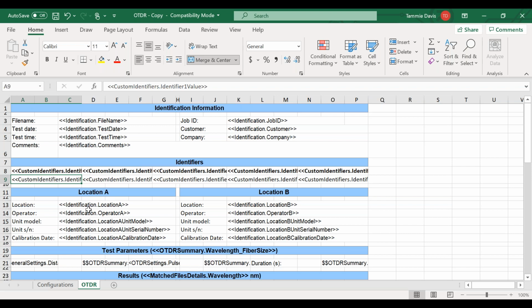If you have multiple files, like let's say you want to do the combination OLTS with OTDR data, and you run the combined report and you probably tested 144 fibers, you're going to have 144 tabs. Or you can save your reports into a PDF where it will have a certain look. It won't have this raw Excel data look.